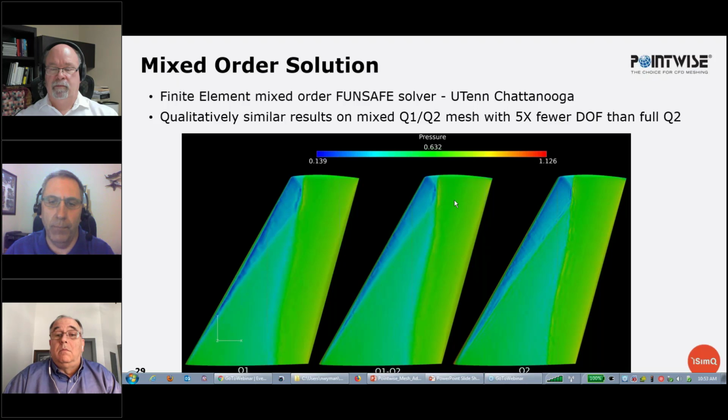The method of generating what we call the size field, the continuous size field in Pointwise for meshing, is independent of the number of point clouds that you have. It knows how to do the set intersection, if you will, of the point clouds. And so I know that Paul found that even the steady cases were more well behaved if he kept the current and previous point clouds around.